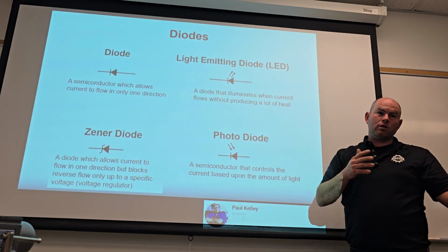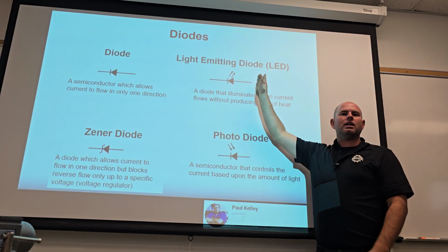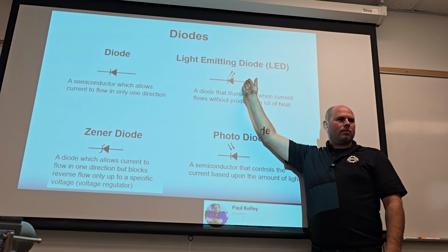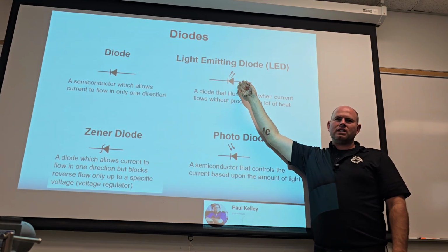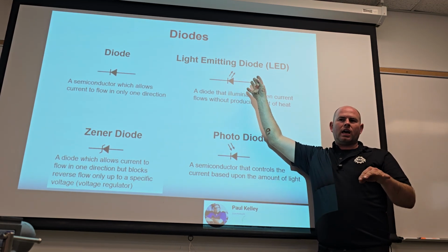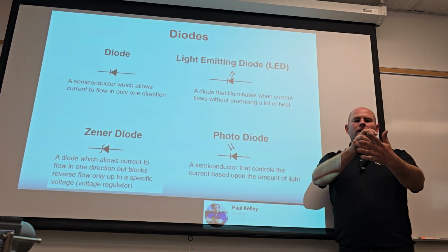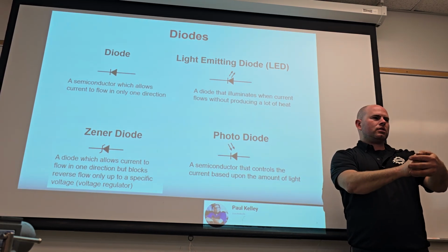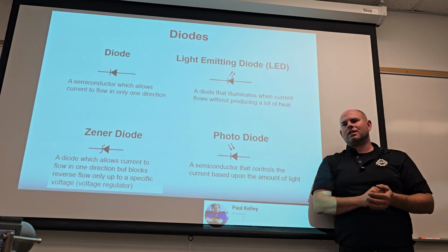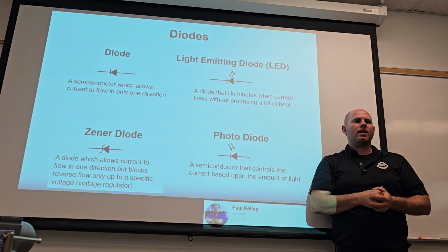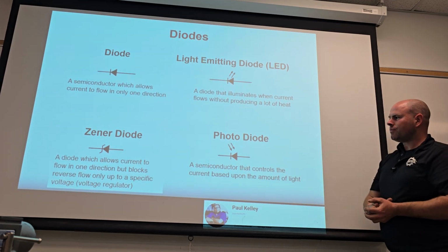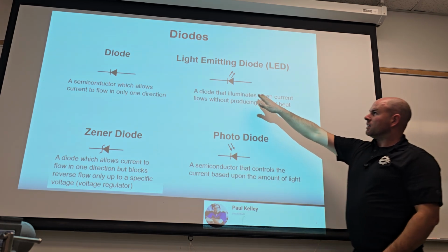So what we would really need to do is make sure that the LED is getting the correct voltage and ground to make sure that it has everything it needs to work. And if it does, then by all means, yes, sell it. But the days of pulling the light bulb out and putting a new light bulb in as your diagnosis are just less and less. Those days are really going away. Kind of makes sense?